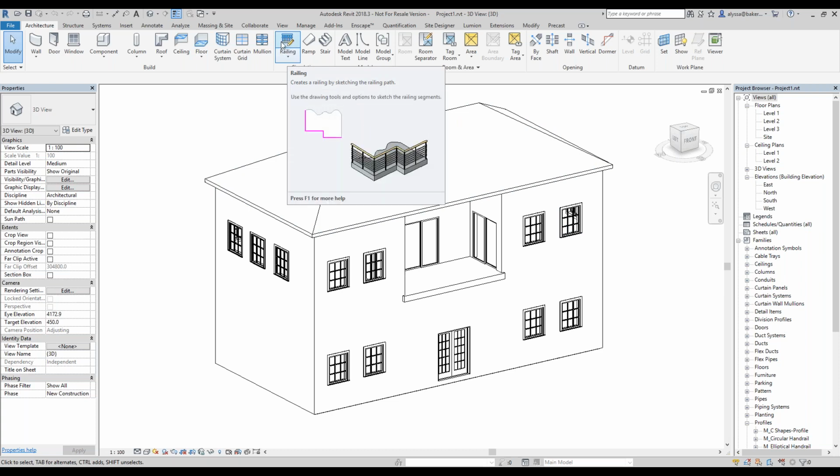What we should understand is that the railing tool or the railing family is a system family. What a system family means is basically it's not like any other ordinary family. You can't just click on the railing and edit it in a family edit mode. There's certain components built into it in different ways. For example, you would have your railing balustrade, your top rail, and your rail profiles, all of those separate components that you can edit, and then join them together and make a custom profile or custom railing for yourself.